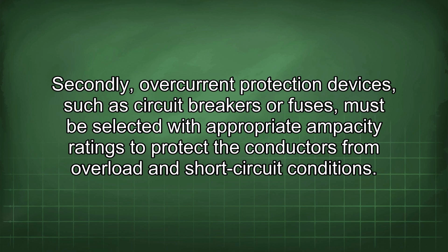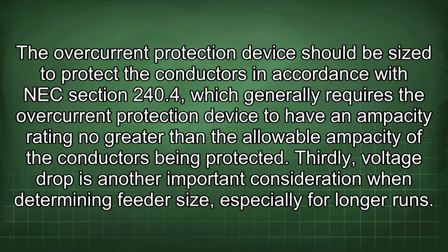ratings to protect the conductors from overload and short-circuit conditions. The overcurrent protection device should be sized to protect the conductors in accordance with NEC section 240.4, which generally requires the overcurrent protection device to have an ampacity rating no greater than the allowable ampacity of the conductors being protected.